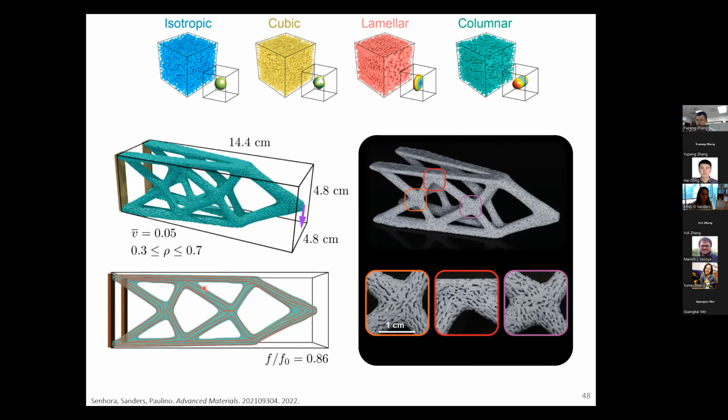And if you look here, you can see these red lines are flow lines through our structure that are indicating the direction of the stiff axis of that columnar architecture. So what the optimization has done is it has kind of realized that it's more efficient to use just the columnar architecture and orient it locally to be aligned with the principal stress trajectories of our structure, or kind of aligned with these sort of truss-like members, okay?